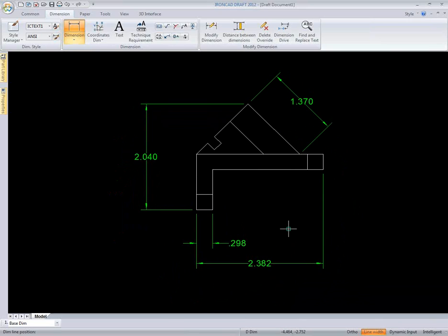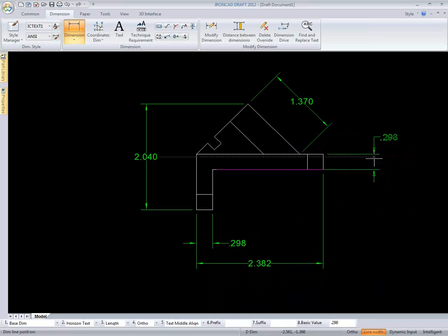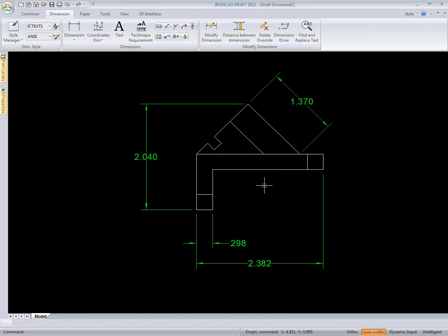How are you choosing whether to go vertical or horizontal on those? Just by dragging the mouse around. It just automatically, like if I'm in here, say I pick these 2 points. Let me grab a couple points. It'll either go horizontal if I'm down here. If I move over here, it'll go vertical. Sweet. It's smart enough with the mouse, yeah. So you don't have to use the tab key anymore. So yeah, that's pretty nice.